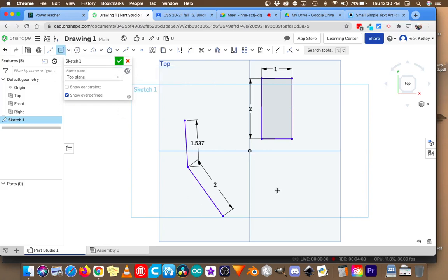So I'm going to use the center point for the rectangle, and I'm going to grow my rectangle based on that. And again, I could just press enter twice to accept those numbers, or I could have changed them. Or I could escape and not use them, but that's generally not your best bet. Now I'm going to go to the circle tool, and this first option asks for a center point and then a diameter. And I'm just going to press enter and accept that.